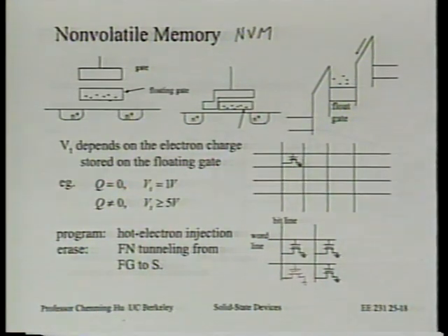Okay? Yes? So when you program, how do you know it's programmed? You have to wait a certain amount of time? Very good. So in all these nonvolatile memories these days, we actually have a state machine included on chip, and what we'll do is apply a short pulse, typically about 1 microsecond, and then measure to see whether it has been correctly programmed.